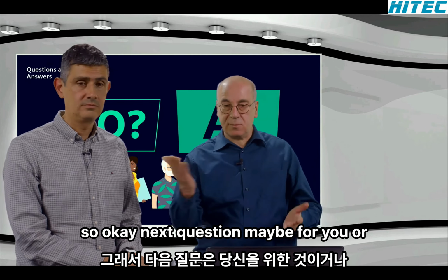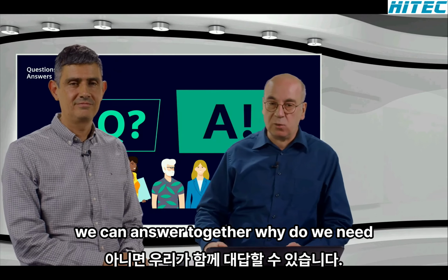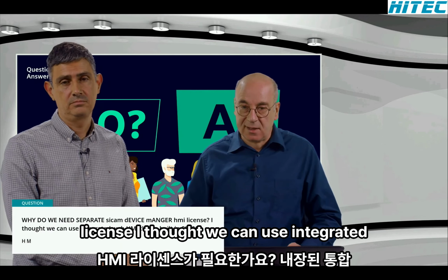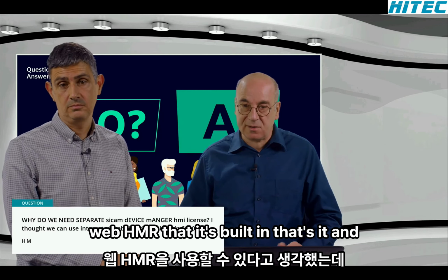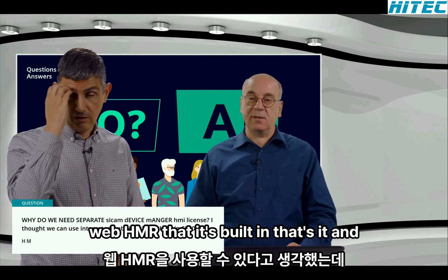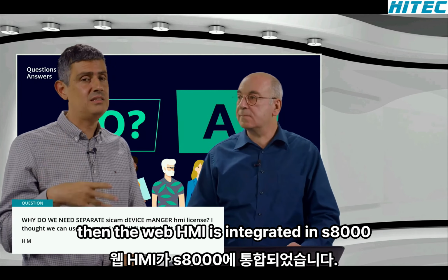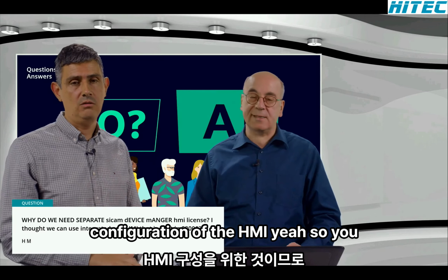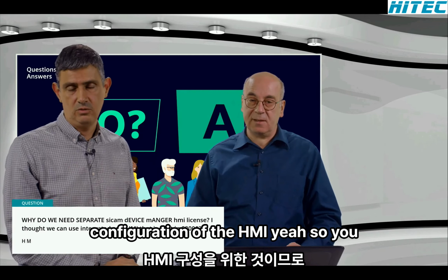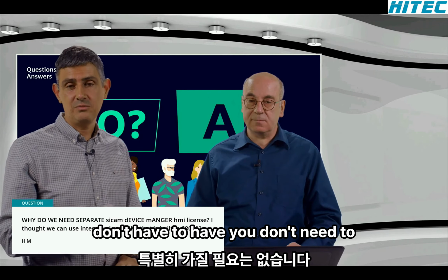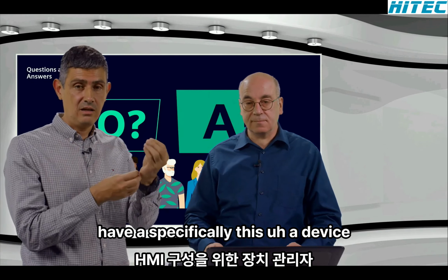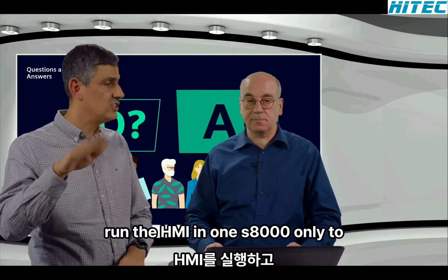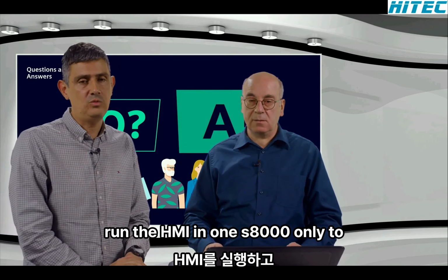Okay, next question, maybe for you, or we can answer together. Why do we need a separate Sicam Device Manager HMI license? I thought we can use the integrated web HMI that is built in. Yes, the web HMI is integrated in S8000. This license is just for the configuration of the HMI. So you don't need specifically this Device Manager license for HMI configuration to run the HMI in one S8000, only to configure it once.